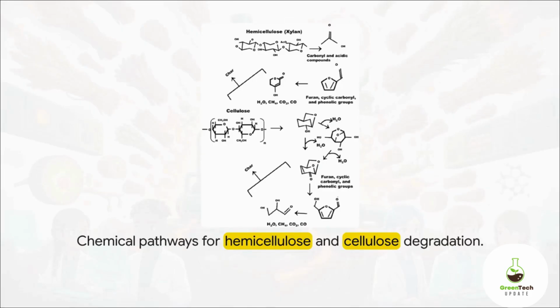Now, these chemical pathways are highly specific. Cellulose decomposition, for instance, happens in a much tighter window. Say your reactor is targeting valuable anhydrous sugars like levoglucosan. To get that, your temperature profile has to tightly control the 300 to 400 degrees Celsius zone. That is the sweet spot where cellulose depolymerizes. If you overshoot or undershoot that window, your yield for those specific carbohydrate derivatives is going to completely plummet.